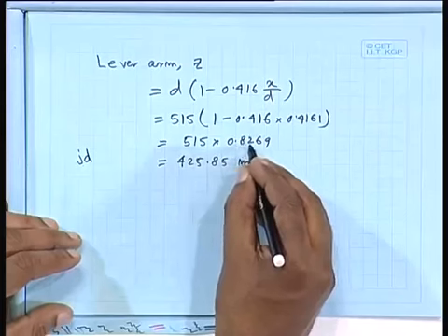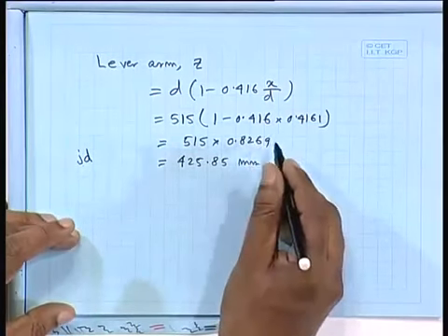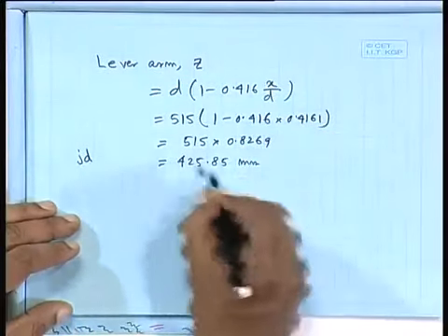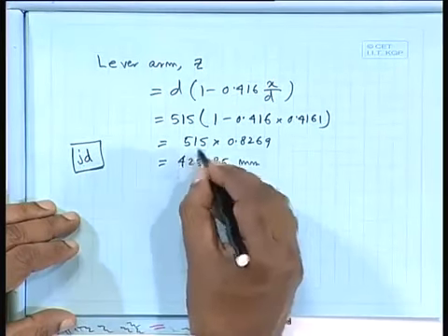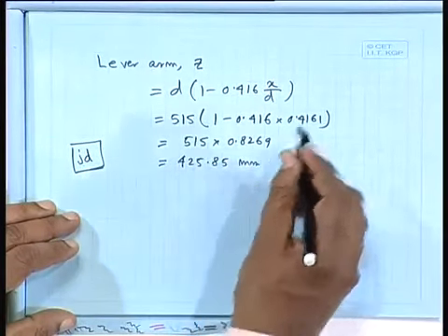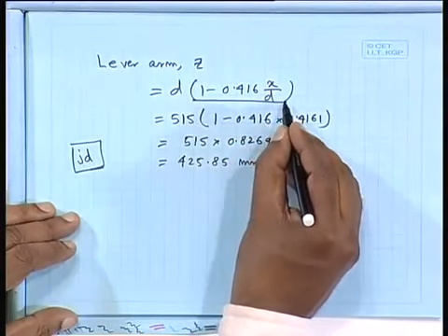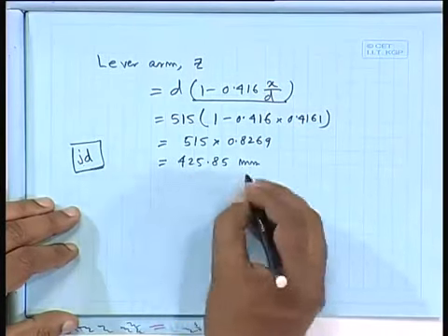So that means here 0.82, 0.85, 0.9, 0.92, something like that. So this is that parameter, the j. So j times d in the limit state method you can find out. So I have got this lever arm Z.